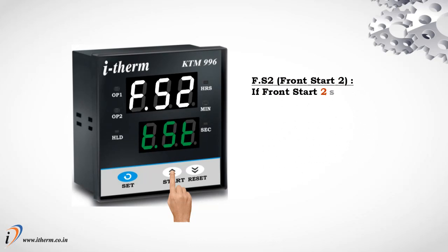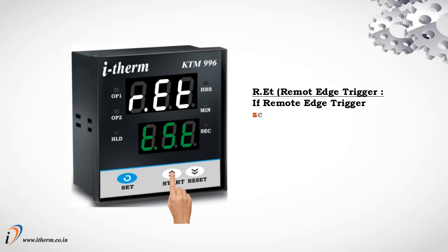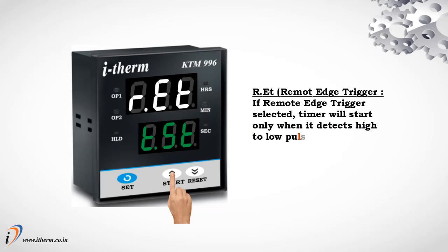Front start 2. If front start 2 selected, timer will start only after user press start key. If power fails in between the cycle, on next power on, cycle will start after applying start command again. Remote edge trigger. If remote edge trigger selected, timer will start only when it detects high to low pulse at back terminal from external input.